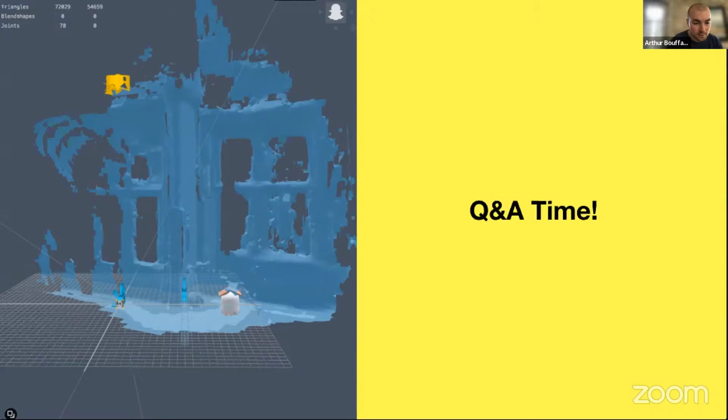So this also answers another question from YouTube, which is scanning buildings that are 6 or 8 meters high. A good thing you might want to do here, and what I did for that experience, is scan a smaller section of the building, maybe an area that people are going to look at a lot, like a specific window or a door, and you scan around that area as a mesh.